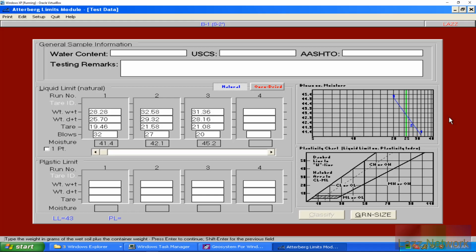So, you can have something called a fatty clay, and you can have a fatty clay that could be over 100% moisture when you do this test. Just saying, in general, you can have that. It's not unheard of, if it's either a fatty clay or something called peat, which is pretty much decayed plant matter. So, dead plants that have decayed and have compacted, and those are usually a dead giveaway because those can hold over 100% moisture by mass. That's organic-like material, as it's called in the industry.